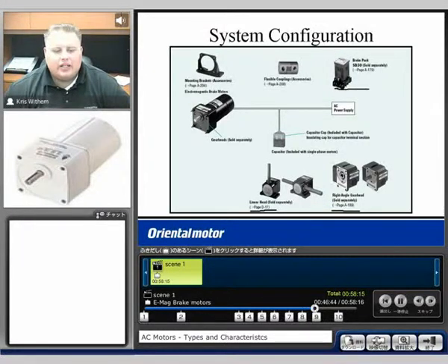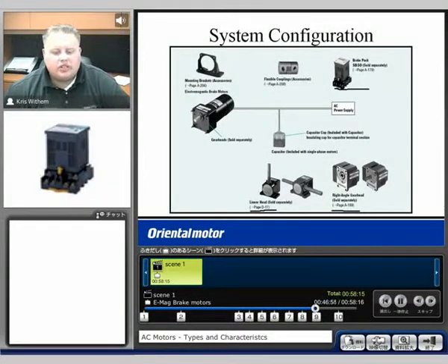Again, this is for instantaneous stopping, so if you were to use the electromagnetic brake to hold the load, but you wanted to stop the motor quickly, the SB50 takes the current away from the motor to help it stop instantaneously. Then your electromagnetic brake would turn on, and you can hold the load in the air or depending on where the position is. A flexible coupling is also available for this type of series, and different mounting brackets are available.